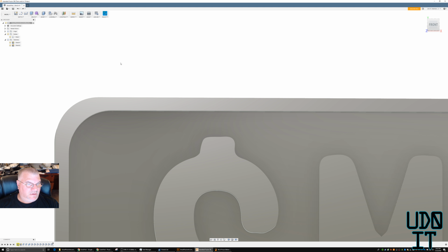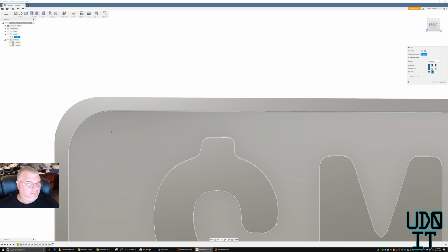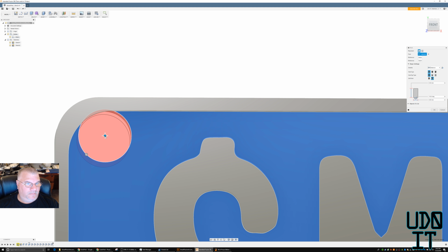So let's undo that. Repeat hole. And we want to make this 8 millimeters. Okay, so it's 8 millimeters.